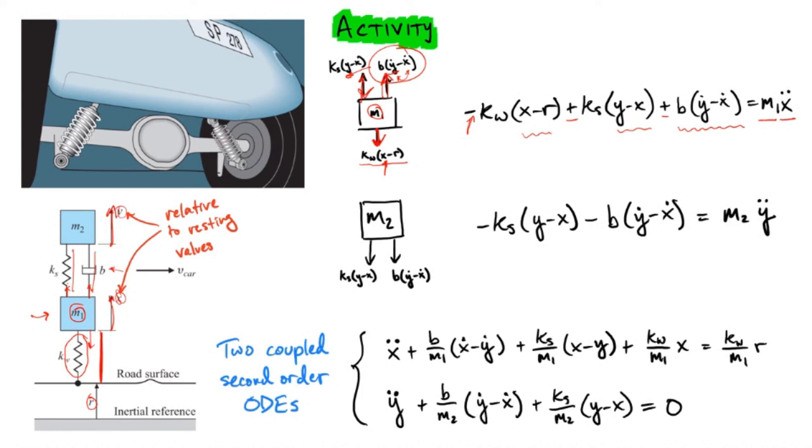So similarly, you can write your block diagram or your free body diagram for mass 2. In this case, it just has the two forces that are attached at the base here. I'm going to write it using the same term, so it's ks times y minus x. And here I've placed the arrow going down because as y gets bigger, that's going to stretch this spring and pull the block back down. And the same thing happens here.